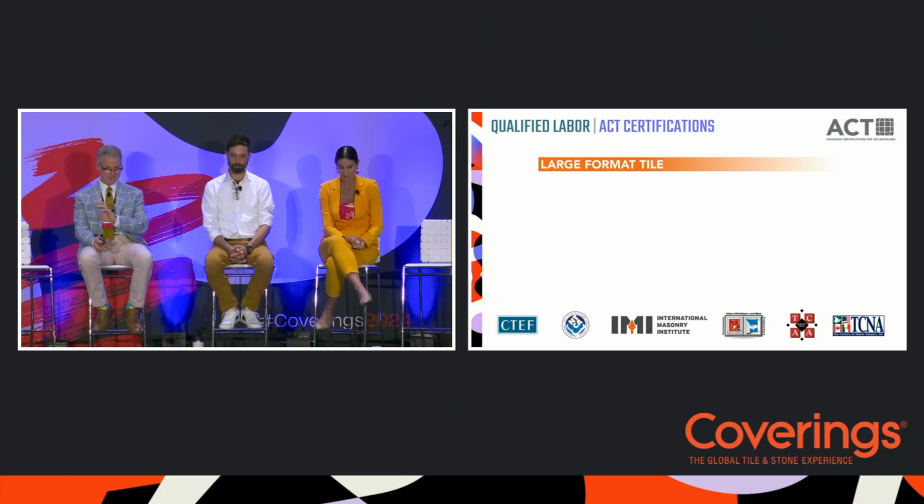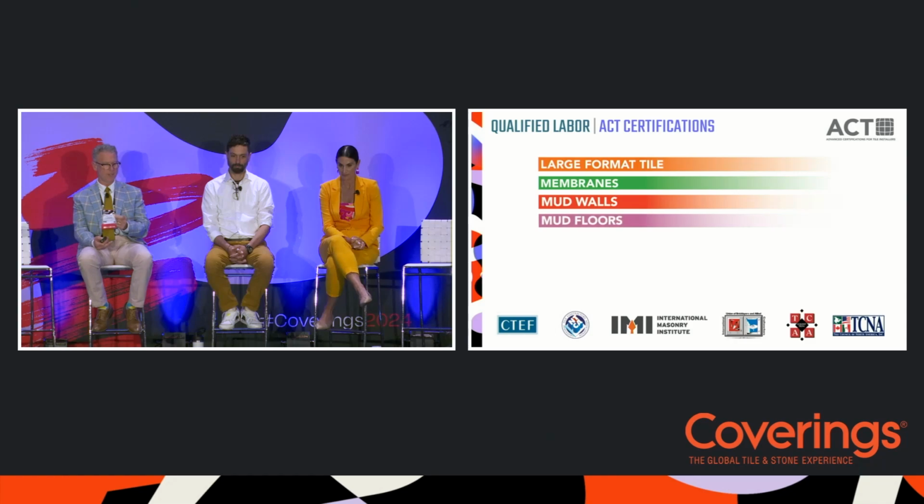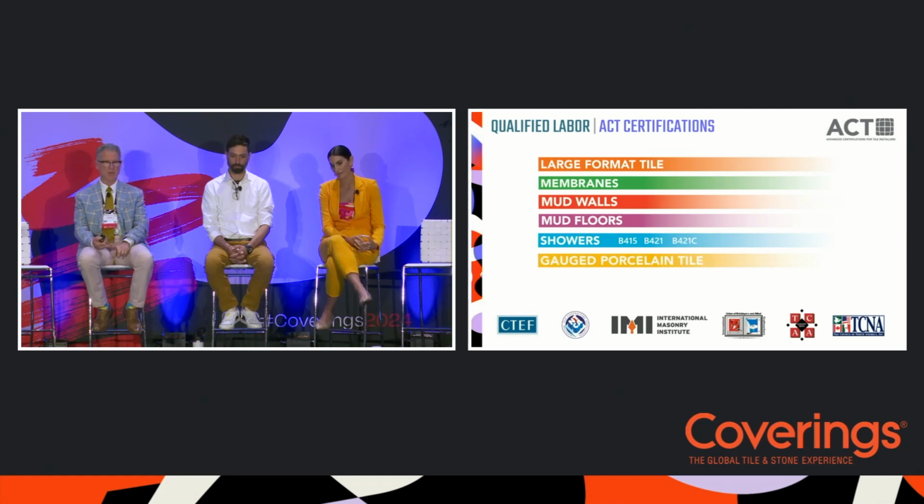So we train them first, and then we test them on large format tile, number 2, membranes, number 3, mud walls, which is a mortar bed wall, number 4, mud floors, number 5, showers, and there are 3 Tile Council shower methods that we train and certify. Number 6, gauge porcelain tile, which is the lamina ultra-large format, and number 7, grouts.